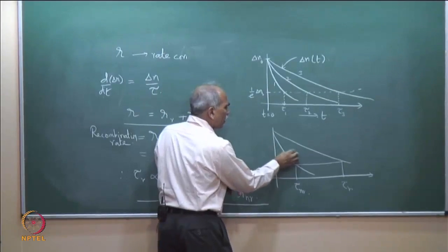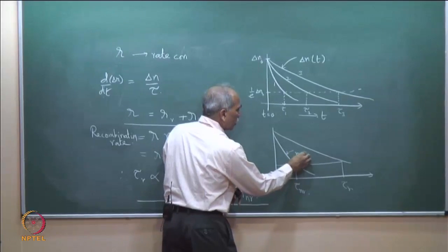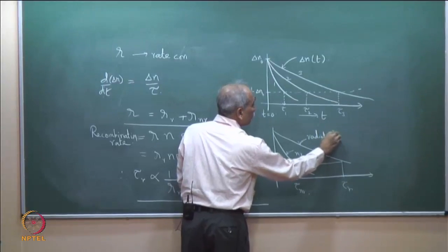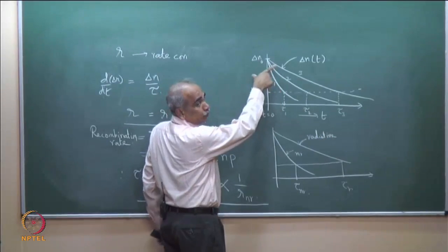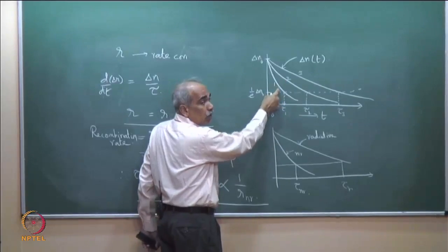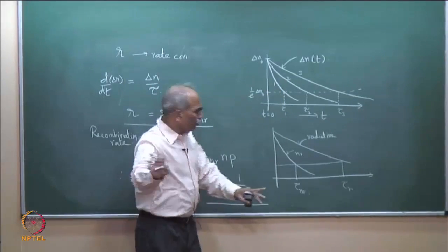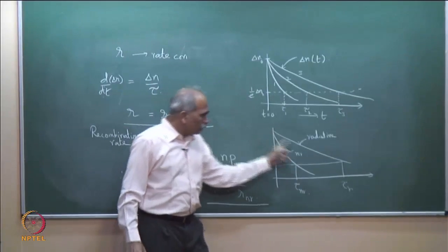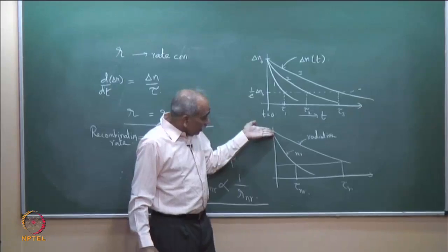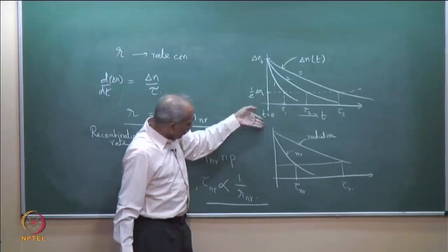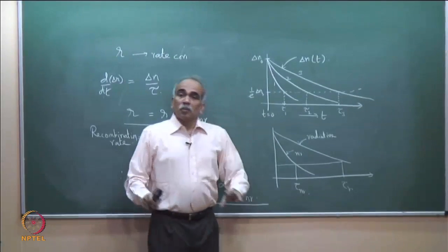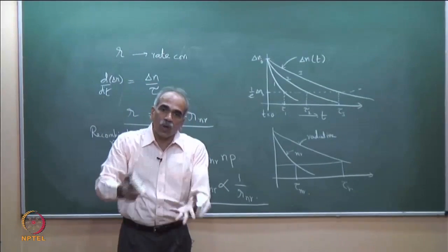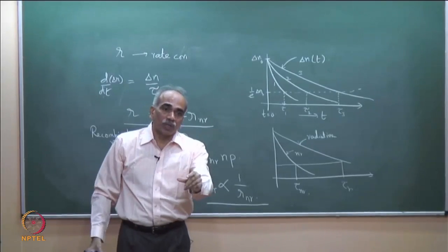Do not worry how we will differentiate between this is non-radiative nr, this is radiative drop, radiative recombination. Here I have plotted the total recombination. So, it is referring to tau. Do not worry about how I have done it right now, I am looking at only non-radiative recombinations and only radiative recombinations. Radiative recombinations are very slow, non-radiative are very fast. But whether it is radiative or non-radiative, one electron and one hole is lost in recombination.